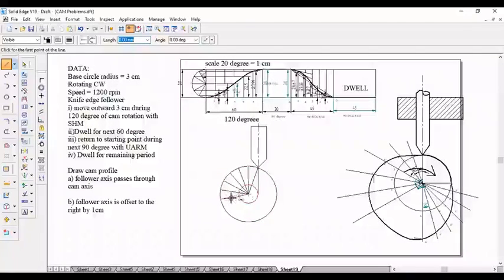This is a 120 degree line. This 120 degree line I divided into 6 parts. But in the previous case, after drawing this line, when we were dividing the lines, we were just extending the lines like this, because those lines itself are your reference lines. So wherever that meets from that particular point, you're going to cut an arc because those lines are the reference line.